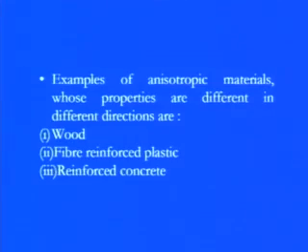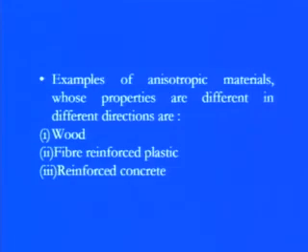And if a material is very sensitive to the load application, at what point of application and at what angle the load is applied, this material property is known as anisotropy. So these are both kinds of features. Isotropy is a very good property that sometimes a material shows, whereas anisotropic materials do not show this relation; they are very dependent on the load application and exhibit different properties in different directions. An example of an anisotropic material is wood.